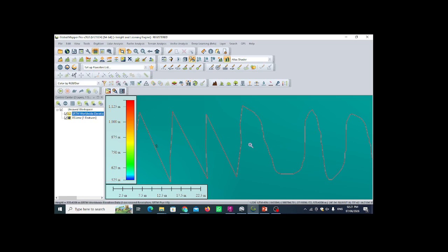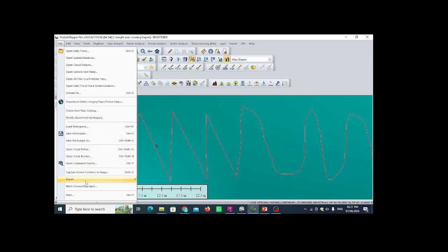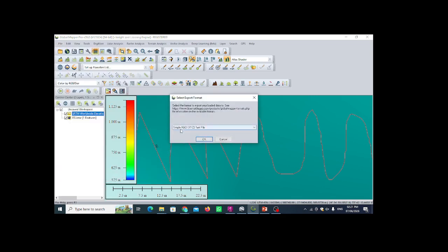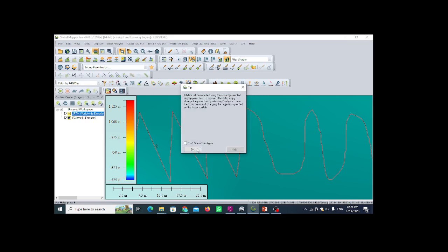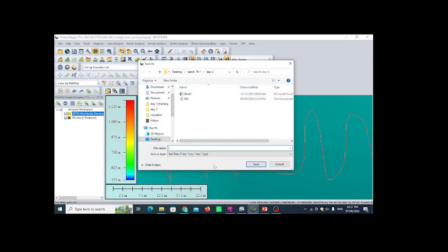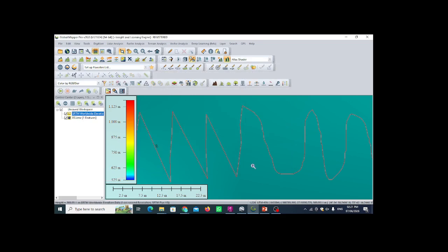Now again we export, because we already set all the export settings. So we go in File, Export in vector lidar format. The same format we set, file format XYZ. We click OK. Then our coordinate is also set, so we click OK again. Then this is our EG data, our existing ground, and then we save the data.